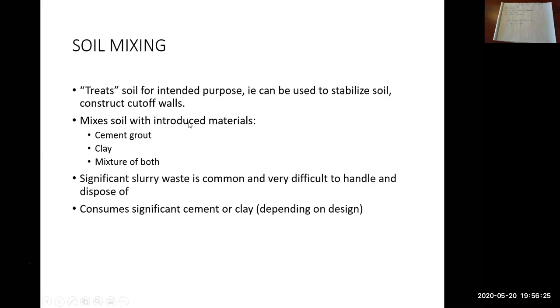This type of system was actually used at the City of Burnaby Works Yard. The ground there was too soft to build the structures on, so a specialized contractor came in and did this soil mixing, soil stabilization treatment over the whole area before the building contractor came in.